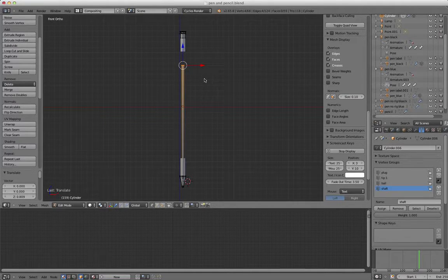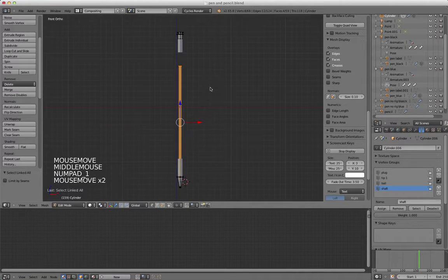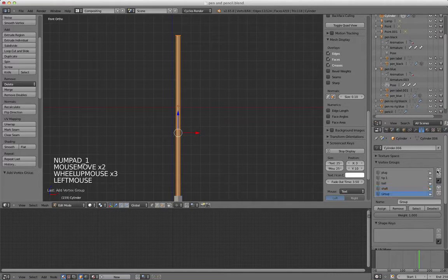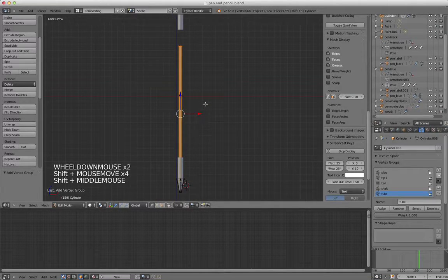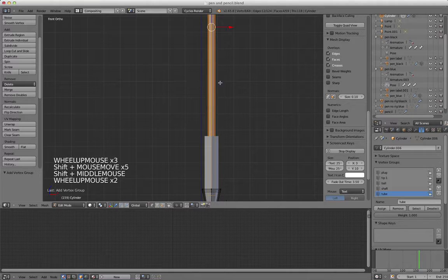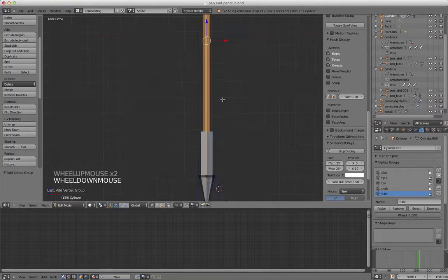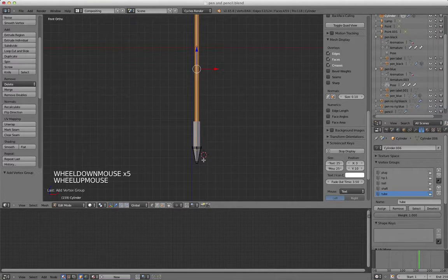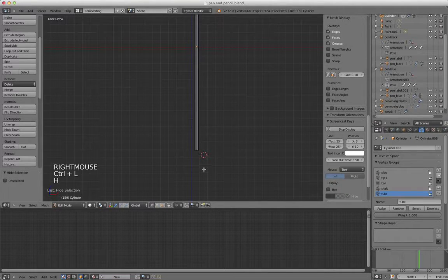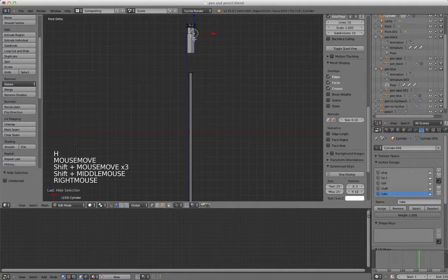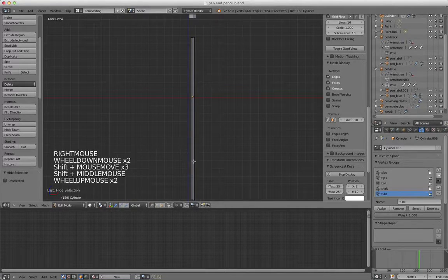here's the tube. I'm just going to hit Ctrl L to select the linked vertices. And let's see, I'm going to add one more, and I'm just going to call it tube and hit assign. So one more vertex group for the tube. The other thing I'm going to do is I want to have some ink in here. So let me just isolate this tube. I'm going to hit the end, Control L again, hide all that. Okay, so now this is just the ink tube.